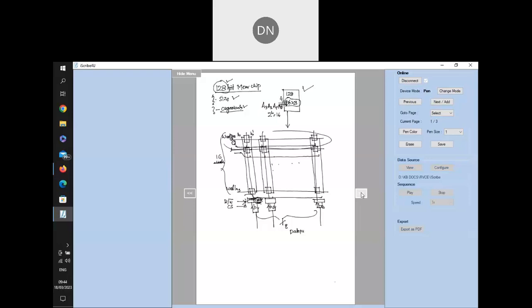That means when the processor generates an address, there should be some circuit inside the memory which takes the 4 address lines and converts them into 16 word select signals. That is why every memory chip has a built-in decoder. Now, what is the size of the decoder? A 4 to 16 decoder. This decoder selects all the word enable lines. That is why, if somebody asks what is the use of a decoder, one of the applications is that decoders are used to design memory chips. Without the decoder, you cannot design memory chips.